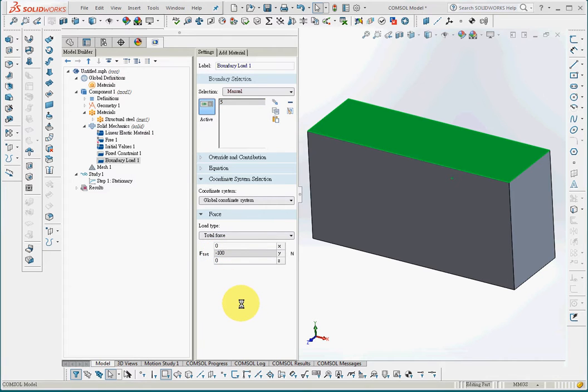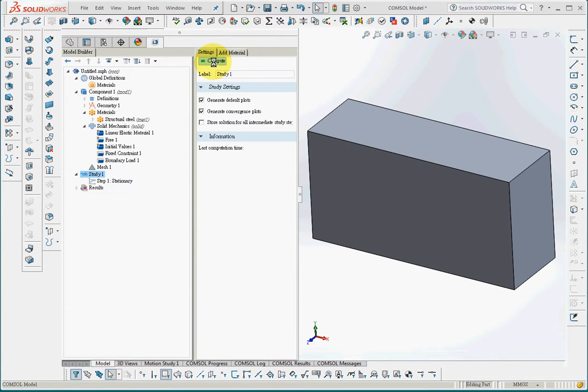So up to now, we have finished with the 4 steps of CAE analysis: the geometry, the material, the mesh, and the boundary condition and loading. And by this time, we have completely defined the problem, and these are called the preprocessors of the problem. And now we can go ahead and implement the computation for the procedure.